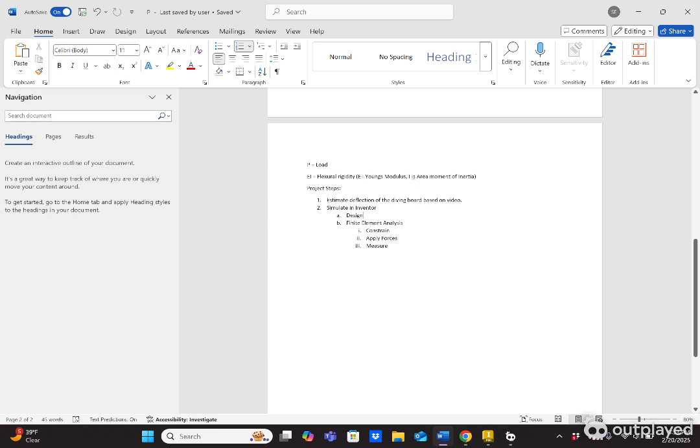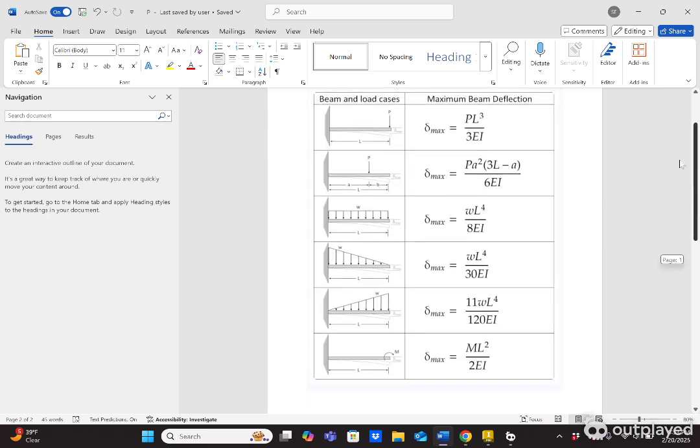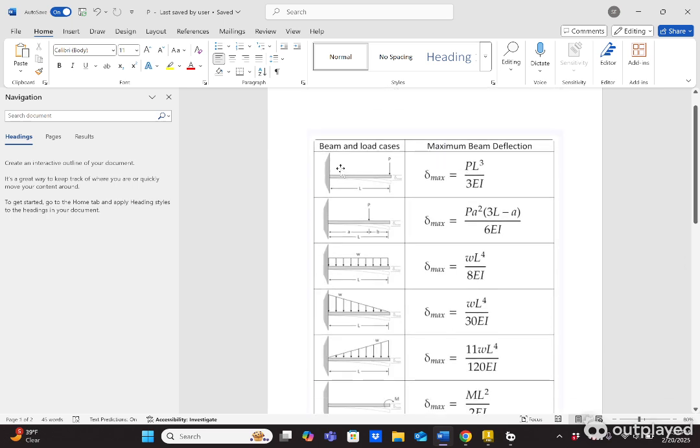As you pick different materials for, like we said, the least weight, the cheapest, etc., it's going to change your Young's modulus. So you need to be able to create a design with a different area moment of inertia to where the product of E times I is equivalent throughout, right? This means it's going to deflect the same amount, not messing up the competition due to a different material being used that's going to affect the deflection, right?